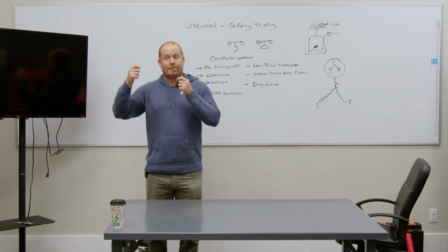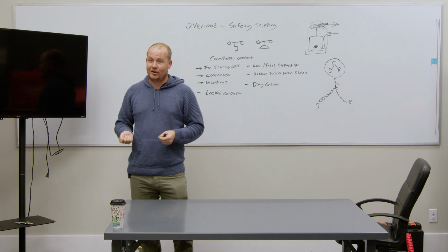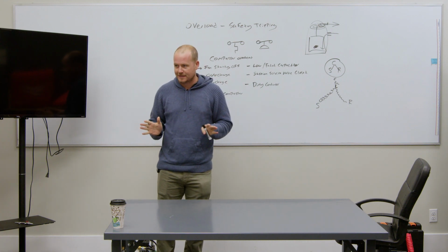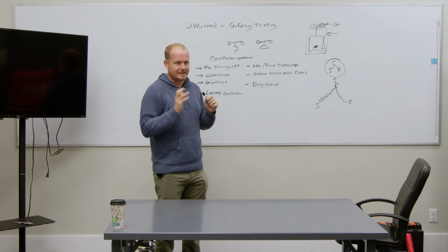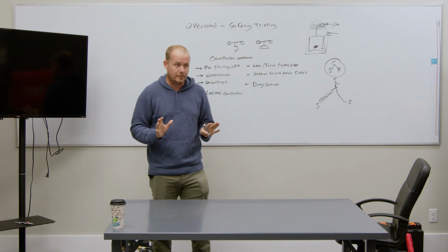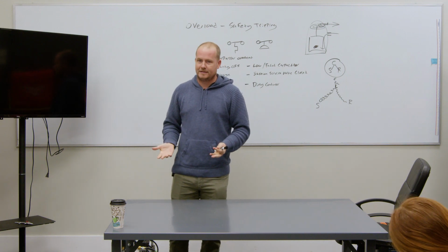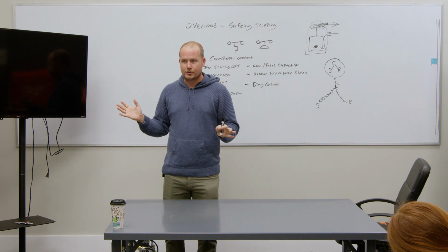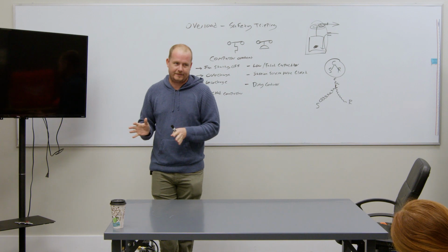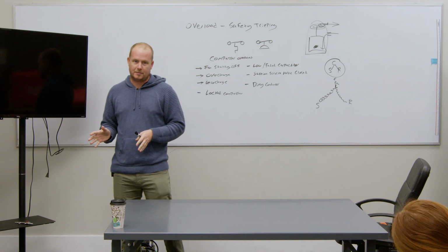Stop it. Take some time. Figure out the cause. Always be focused on the cause. And this is how I want to end this class. Anytime there's a safety, and a thermal overload is a form of a safety, anytime there's a safety that's open, yes, diagnose what safety is open, good job, use your meter, all that stuff. But even more important is what caused the safety to open. Why did that happen in the first place?